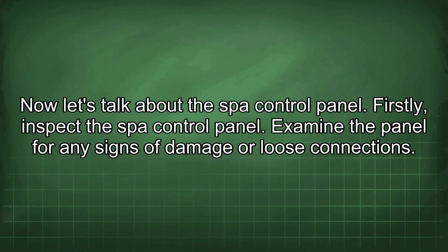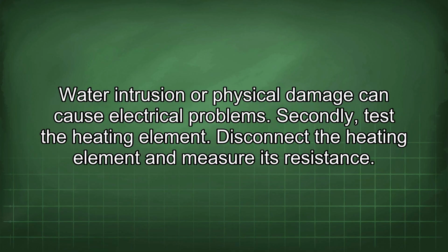Now let's talk about the spot control panel. Firstly, inspect the spot control panel. Examine the panel for any signs of damage or loose connections. Water intrusion or physical damage can cause electrical problems.